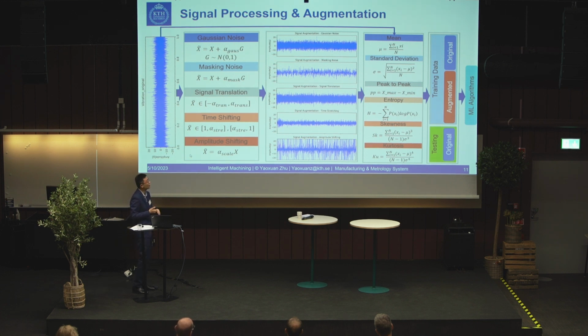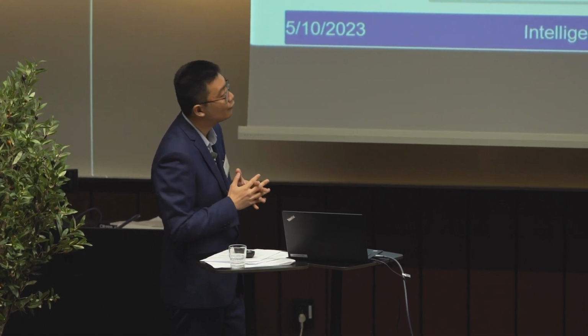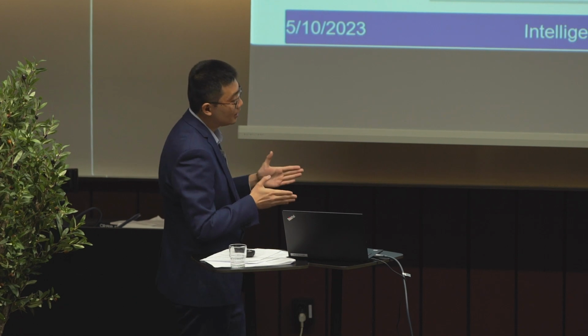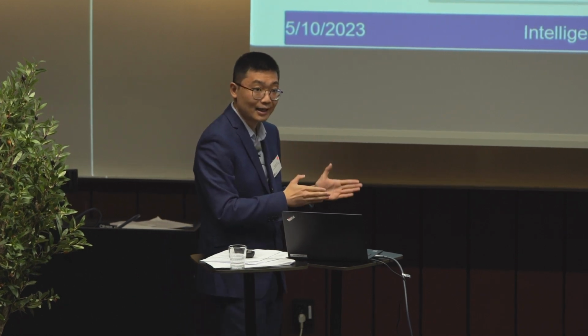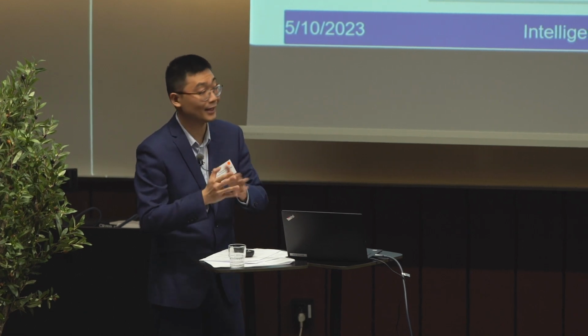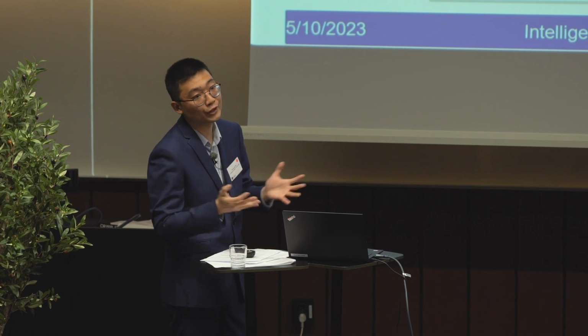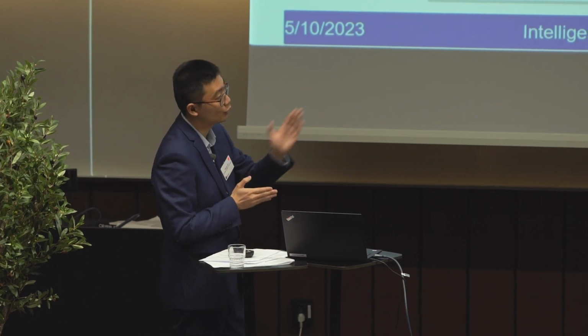Statistical features like the mean value and standard deviation of the vibration signal can help us extract useful information from those signals. And later, when we have the augmented signal data and also the original signal feature data, previously we only used original feature data divided into 2 groups.